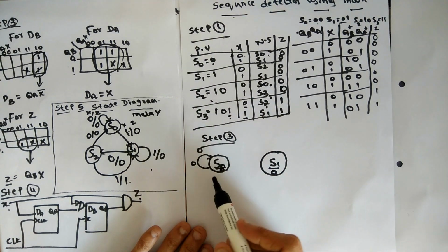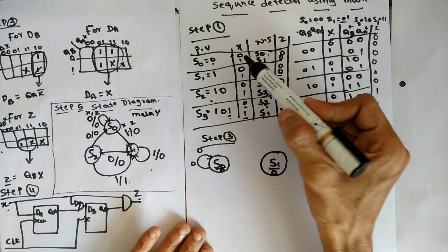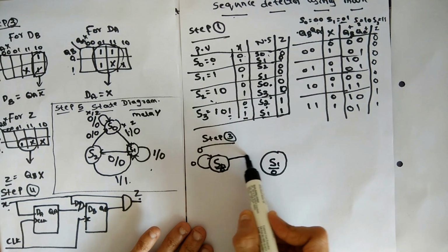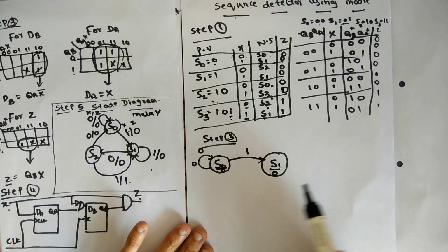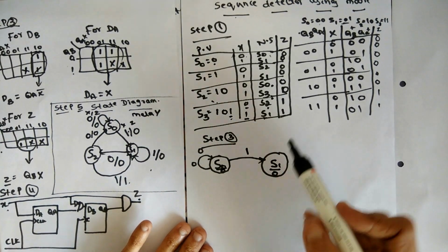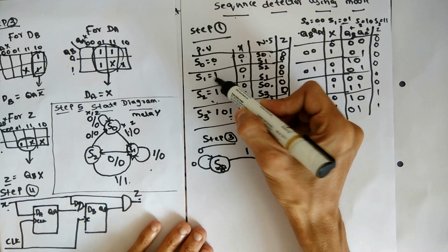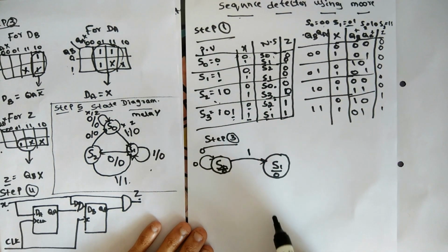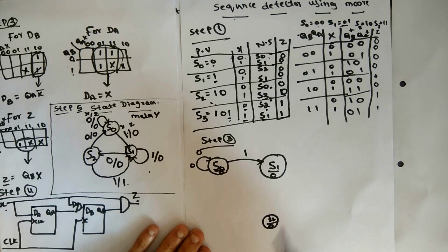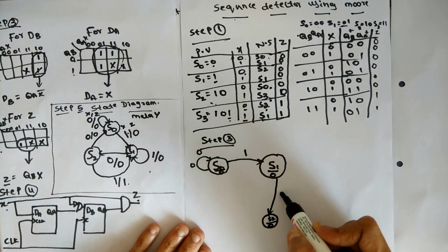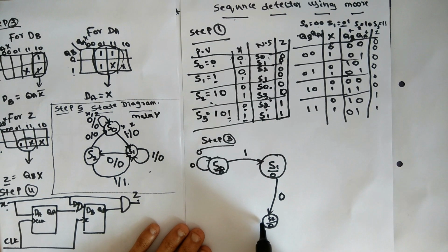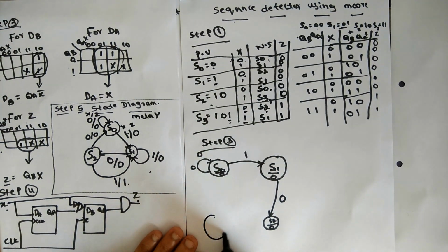Okay, and then the state of S0 is 1, it is going to S1. So when it is 1, it is S1. Only write input and output inside the circle. So in the S1 state, when 0 it is going to S2. So write one more portion called S2, and the S2 output is 0, write 0. So S1 is when 0 it is going to S2, so make it 0 S2, and when 1 it is going to the S3. So write S3 here.